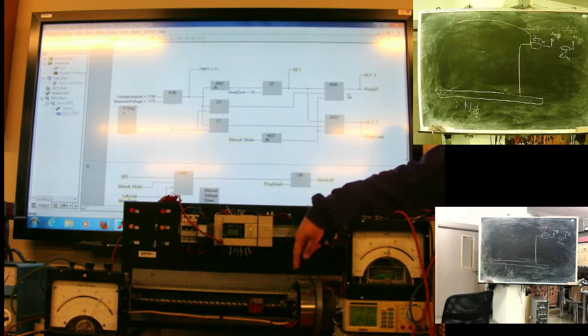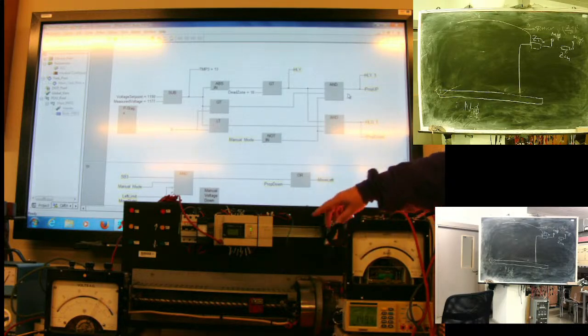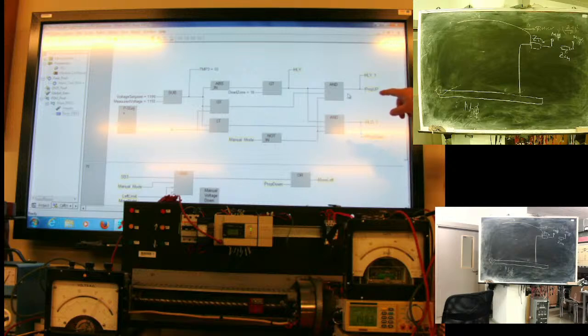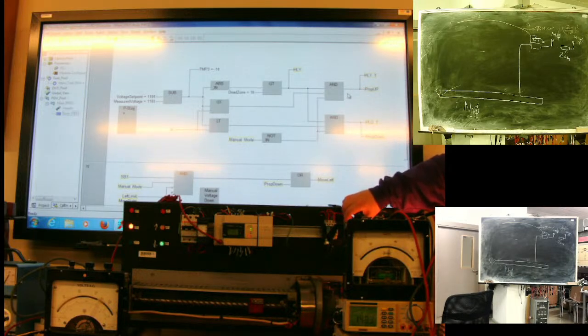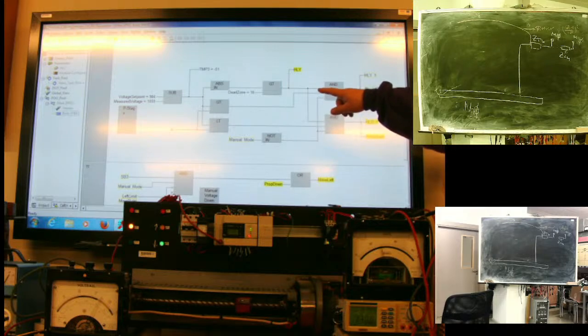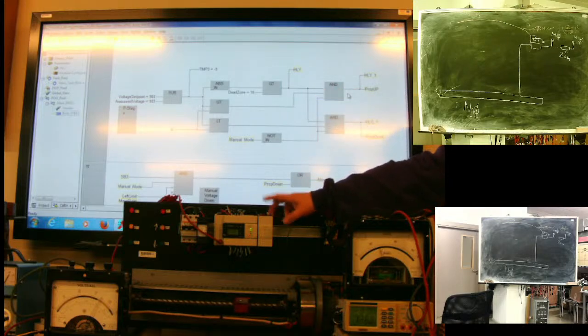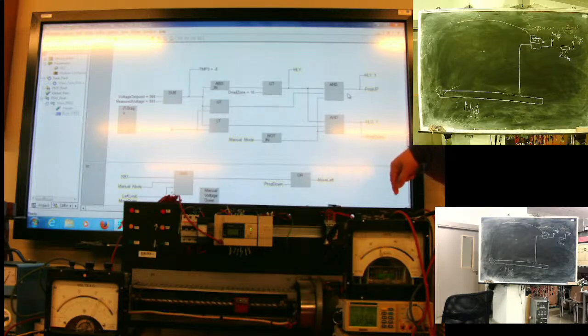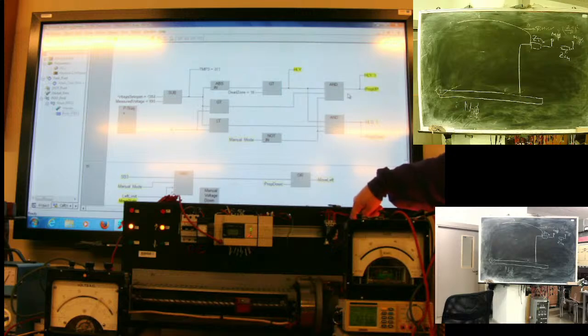Rheostat, motor driven. This is analog to digital converter. This is brain processor. It's what's going on inside. It has two voltages. One is set point, set by this tiny knob. It's a small rheostat. And another value is from second channel. It's a low voltage. The system tries to keep them equal.